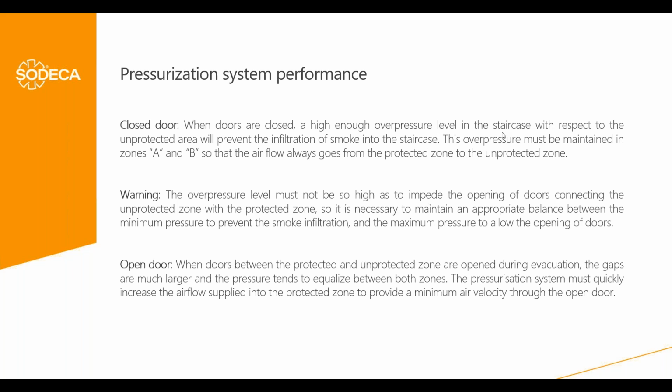This 100 newtons will correspond to a certain level of overpressure, depending on certain parameters like the dimensions of the door, width, height, the force of the self-closing mechanism, the distance from the handle to the hinge, etc. So there is not a fixed value of overpressure; it's a fixed value of force to open the door, but this force corresponds to different levels of overpressure.